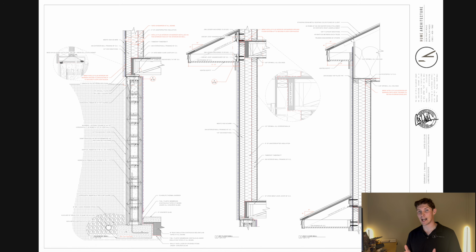If we need to accommodate R30 cavity insulation, you either need to expand the actual width and depth of your wall construction so that you can fit in the proper amount of insulation. You need to plan for exterior insulation, how the siding comes together, your weather protection on the exterior, or we need to think about other materials, spray foam, other things like that in that nature, which all comes into how we detail each of these drawings.